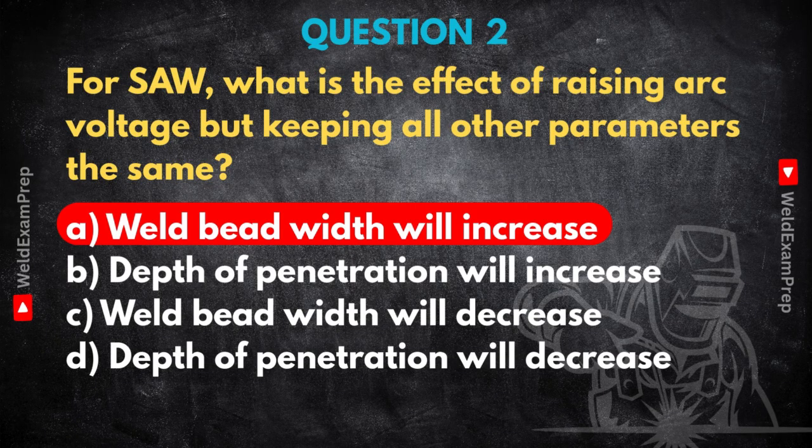And the result of that is a wider, flatter weld bead. Because that energy is spread out, less of it is focused downwards, digging deep. So the penetration depth often decreases, or at best doesn't really increase much. Right, the energy density drops. Exactly. If you actually want more penetration in SAW, the main thing you adjust isn't voltage, it's the welding current. Amperage is key for penetration there.